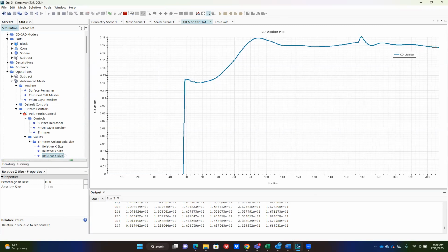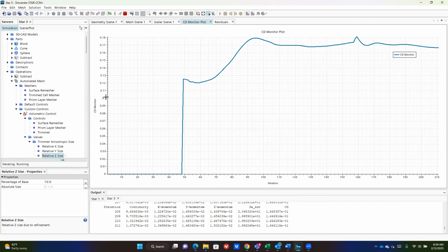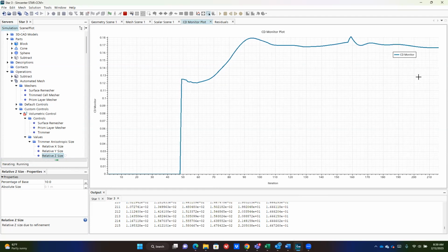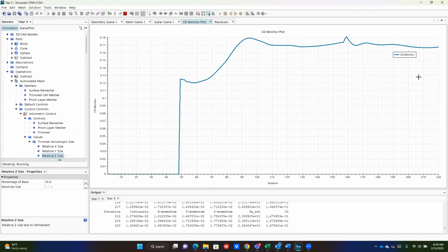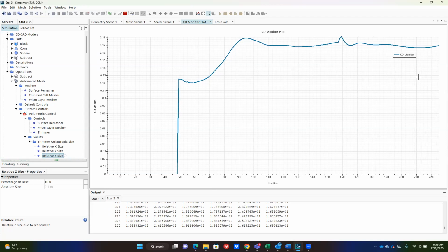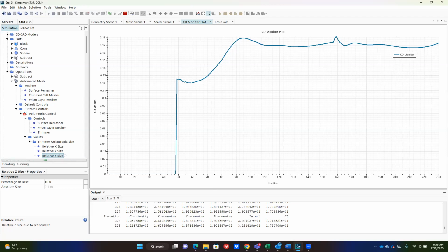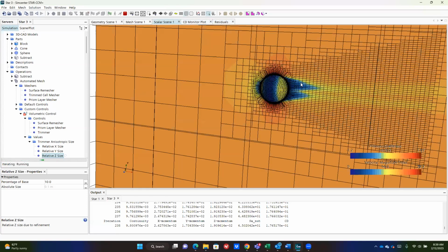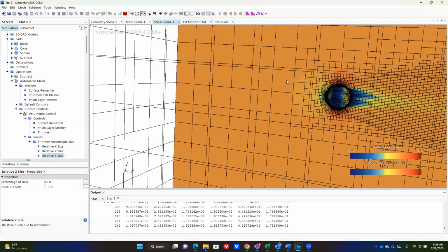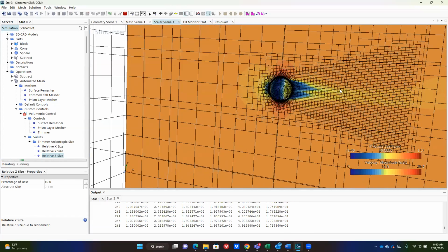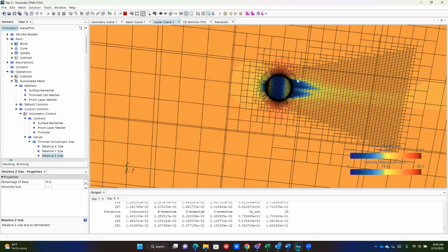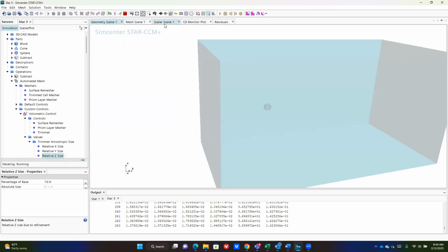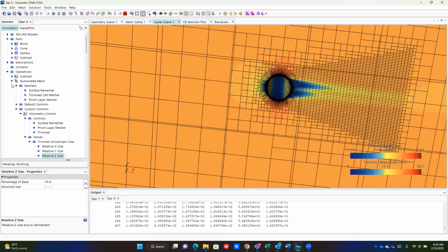One thing you have to be careful of is your drag coefficient. If you're comparing with theory or a base value, make sure you defined the drag coefficient in a way that's consistent with however it's reported. If you're looking at the solution, one piece of general feedback would be, okay, this is probably too big. I could probably add more mesh in just this region to really push this out. And this is more or less the general differences in 3D, and I think it highlights them.